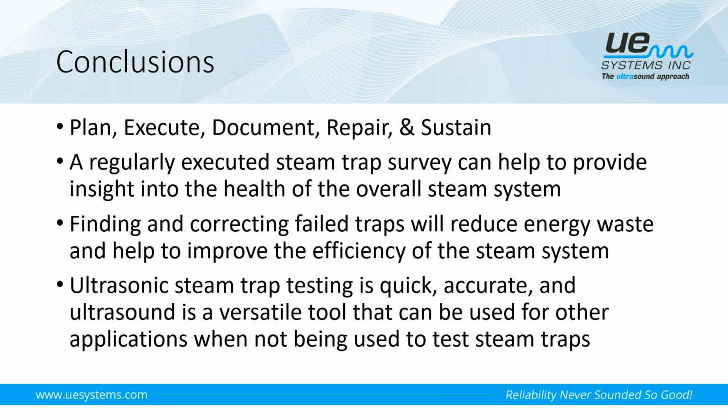But a regularly executed steam trap survey, again, can help to provide insight into the overall health of the steam system as a whole. We can make these corrections to the traps that are leaking by or failed, and we can reduce energy waste. And for some of you, depending on where you're located, how the steam is generated, it could be very expensive. So we could be talking about, into the tens, if not hundreds of thousands of dollars the first time you go out to do your steam trap survey as far as your findings.